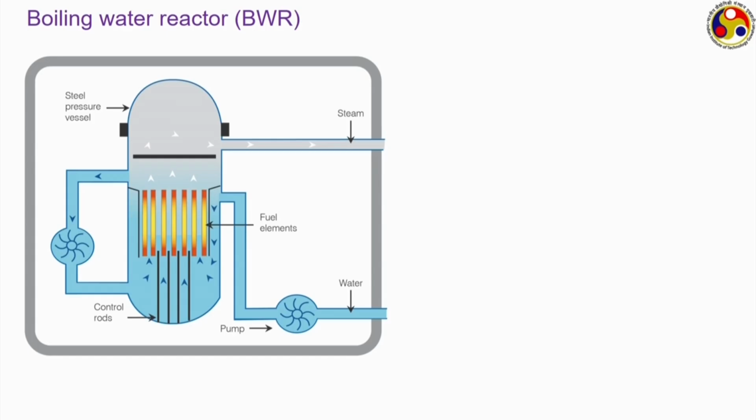A boiling water reactor is the counterpart, where again we have a big pressure vessel just like this, but inside we do not have any pressurizer kind of component which can control the pressure, and therefore, once the heat is supplied, the liquid temperature can increase up to the saturation temperature level and may start boiling. So, in case of a boiling water reactor, the liquid enters the tank from somewhere here, or if I draw properly, it is entering the tank from somewhere here like this.